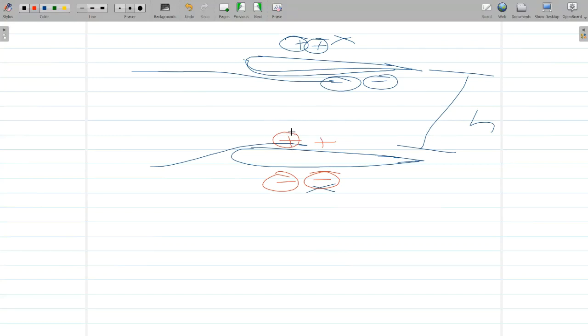So as you know, flow will always tend to go from a region of positive pressure to negative pressure, right? Or let's say from high pressure to low pressure, to be more accurate. So this region has lesser pressure than this region, and they are in the same domain, right? They are not separated by anything. So you could typically expect your flow to move towards the sky. So you see the flow streamlines moving towards the sky.